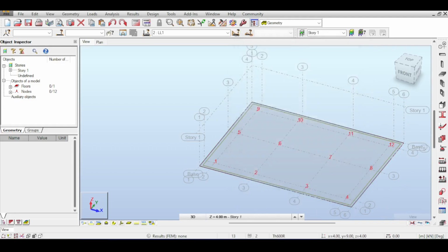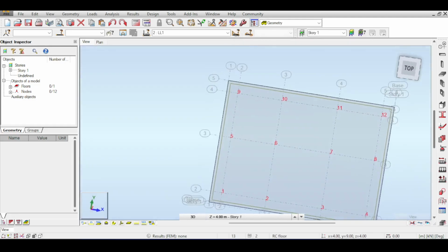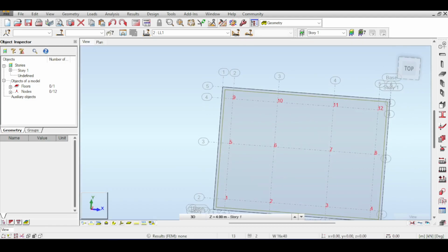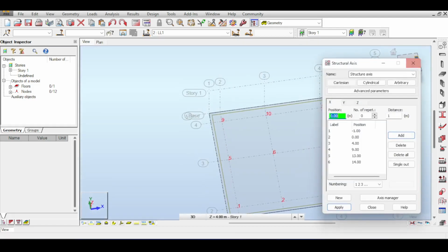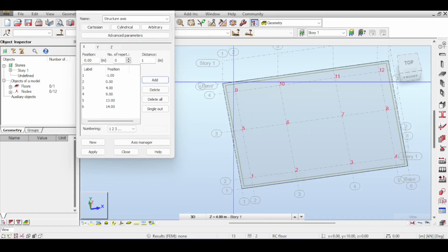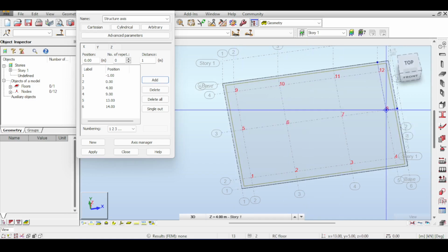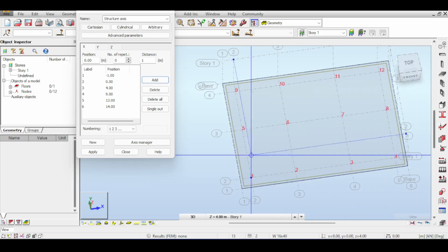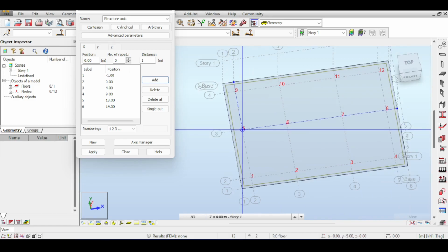And I will assume that there are some areas here. Let's say that this column is responsible for this tributary area. And I have to calculate this off screen very quickly. I need to find a quick estimation for the load. So give me a second. I'll do this off screen. Or I just thought maybe you want to see this very quickly on screen. So I'll click on the structural axis and take a look. So I have 3 types of columns, maybe 4. I have the corner columns, and I have the middle columns. I will assume that all corner columns are the same just to speed up the calculation.